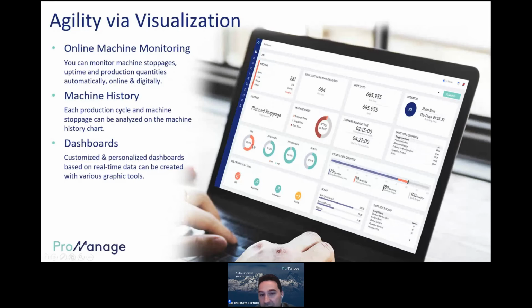You can see the OEE values: availability, performance, quality values. You can see the trends of those OEE values in the last hour. So the OEE was going down, the other metrics were stable or up. You can also see the production quantity. The machine has produced 70 in the work order. It's missing 10, which means the machine is behind schedule. Current production was supposed to be 80, and the shift target is 100. You can also see shift top 5 scrap values.